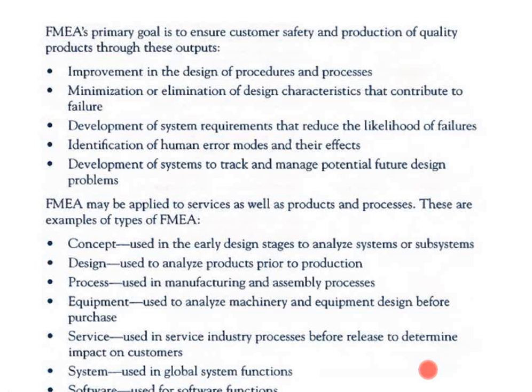Because it's 36 inches, fall protection is required when someone works on a roof, which means they have to harness in and have anchor points. If we just built that parapet 6 inches higher, fall protection is not required anymore. We actually eliminate a hazard where people are going to be working on roofs. So that's an example where you can say, how can we eliminate a failure, or at least make it less likely. Now we comply and we can reduce costs by doing so.